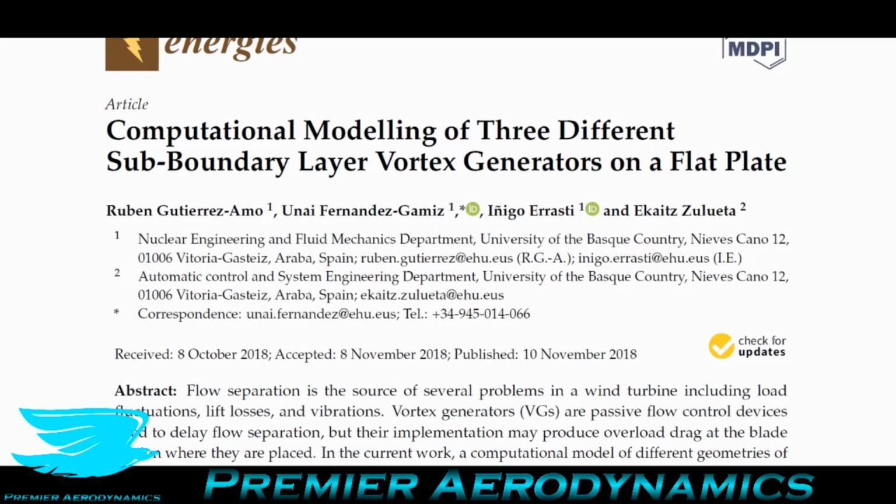So you create vortices. These vortices spin around inside the boundary layer. They pull higher moving, faster moving fluid, or high momentum flow as the typical term is, and push it into the boundary layer near the surface. That re-energizes the boundary layer there and allows the boundary layer to travel further over the surface before you then get this flow separation occurring, before the velocity goes to zero, because you've now given it more energy. And it reminds me of that Arnold Schwarzenegger song by Luke Millions. Anyway, it gives it more energy and it prevents stall.